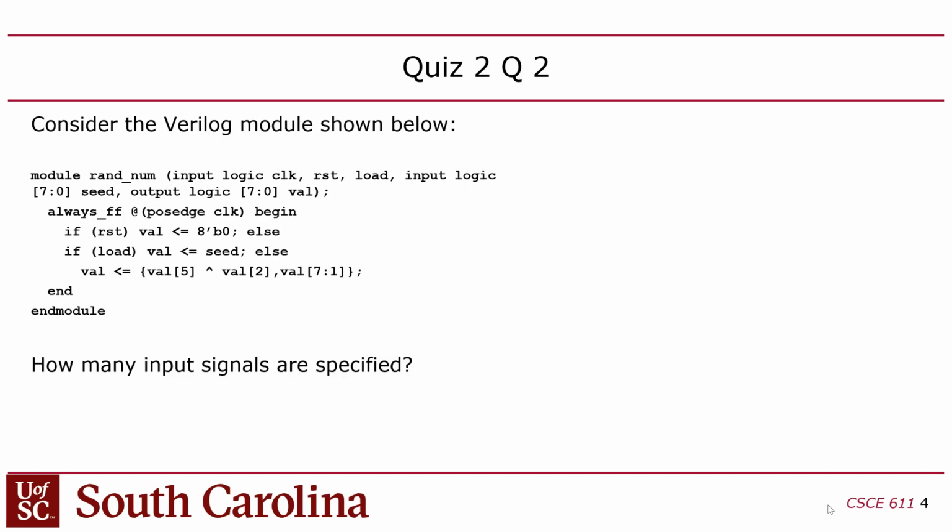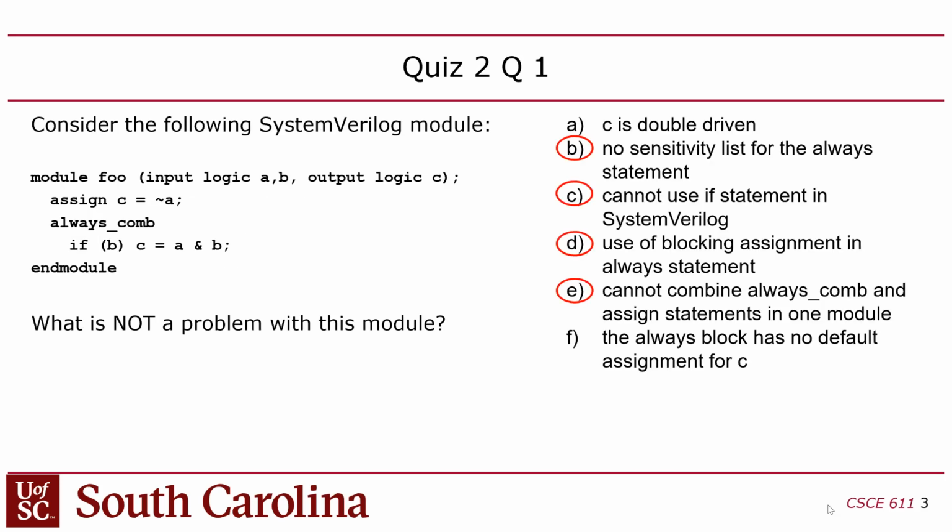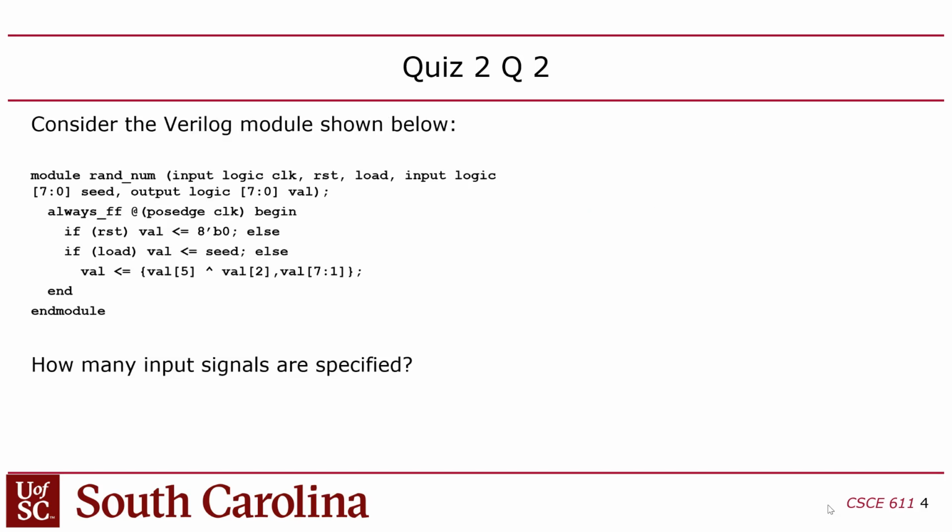Did you say that an always_comb statement in general is always sensitive to any input to it? Any input, yeah, which means anything that appears on the right-hand side of an assignment statement or any signals that are part of a condition. If we were writing Verilog, could we specify more things to be sensitive to, even if it's redundant? You could. I don't think it would make any difference, though. You would probably do always star and then additional steps. Well, you could just say always at and then list them in the parentheses.